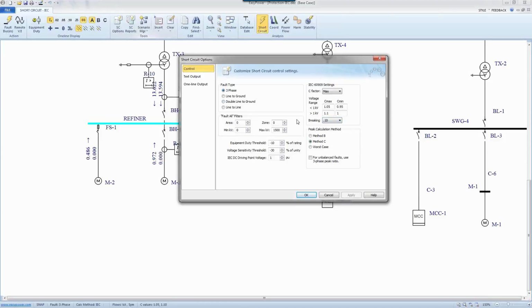So if you don't choose that braking current in TCCs, and I will cover it either in this presentation or future presentations in much more detail, this is where you choose the braking default as a global option, unless you go and override it in other studies somewhere else, because we have 4 different types of braking. So wherever you see a name of braking, if you didn't override the value, braking 100 millisecond or 0.1 is the one that EasyPower will go and pick.